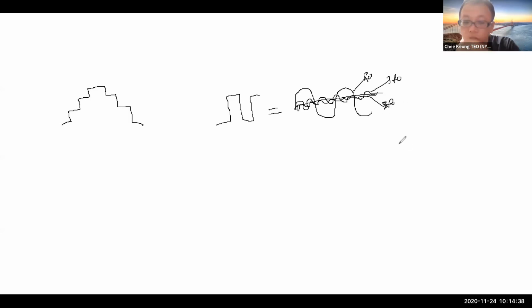If you look at the frequency domain, it basically looks like that. With your fundamental being the strongest, which is F0. Then you have your 3F0 that's coming in quite strong, but slightly less so. Then you have a 5F0 and your 7F0, so on and so forth. You're getting smaller and smaller and smaller, right? So your square wave essentially is made up of your fundamental frequency F0 here, and the rest of the harmonics.